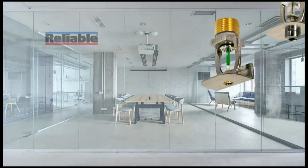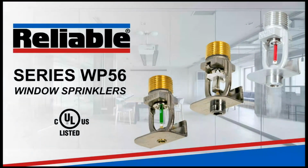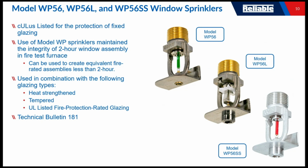First sprinkler we'll focus on today, there's multiple models of it. It's actually our WP series window sprinklers. Now, a window sprinkler is a product that is UL listed for the protection of fixed glazing. What we do with this product is that we take it to the laboratory and we try and evaluate it to make sure that it can withstand fire conditions for a certain time duration. We focused on up to 2 hours because this is meant to create a situation where you can use a sprinkler instead of building a fire-rated wall for up to those 2 hours.